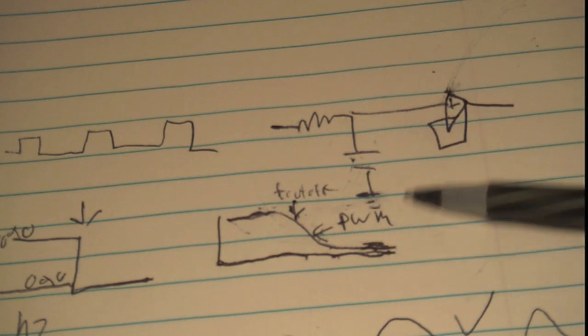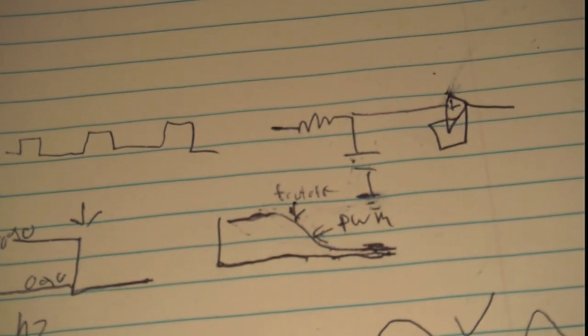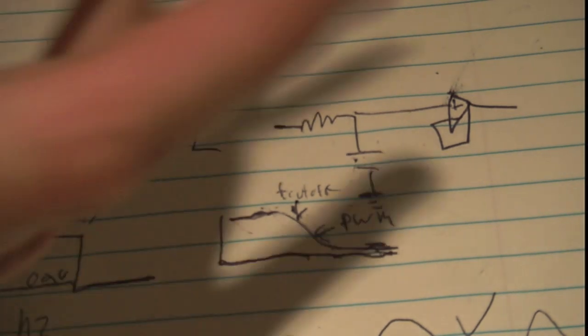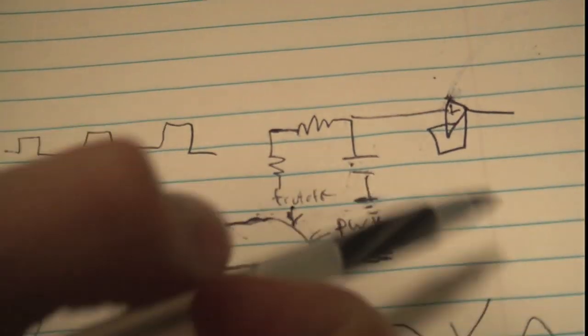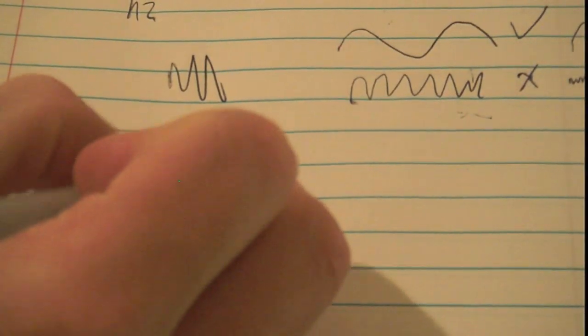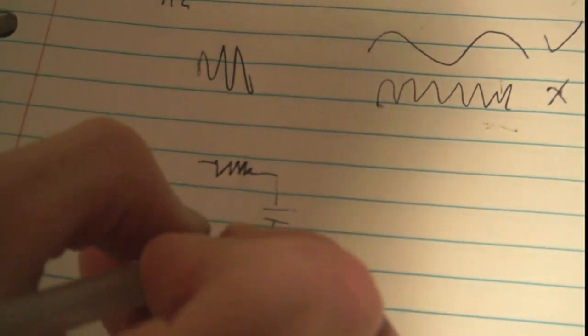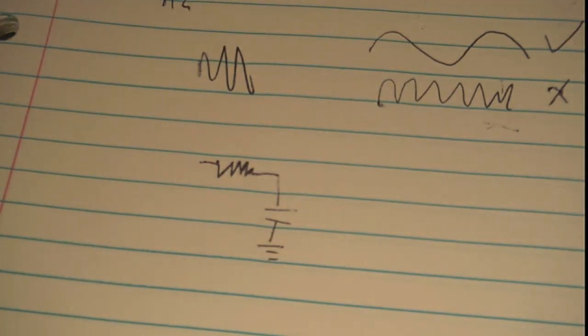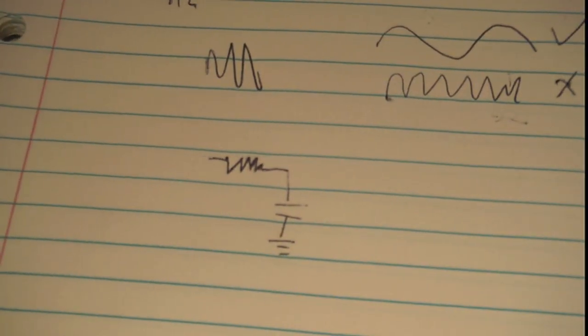Since this is a passive filter, it's going to be influenced by any resistances, extra inductances, extra capacitances that are anywhere on our filter. So a resistor on the input, that's going to influence it. A resistor on the output, that's going to influence it. Obviously there's going to be stray resistance and capacitance whatever we do, but we really want to eliminate this as much as possible.